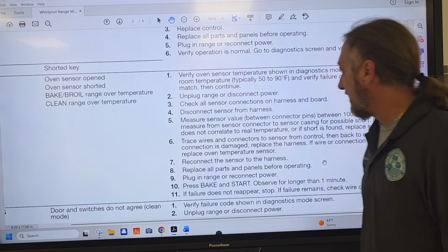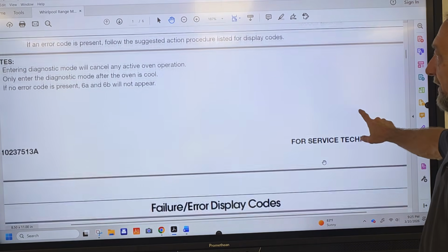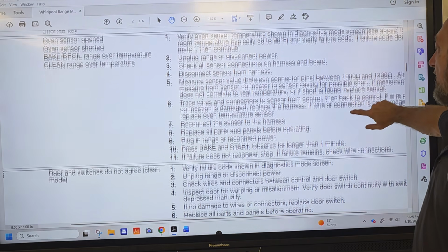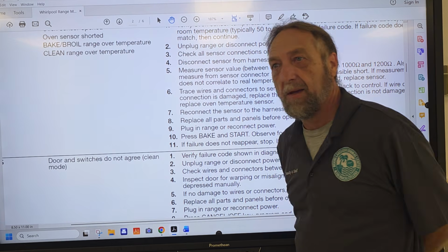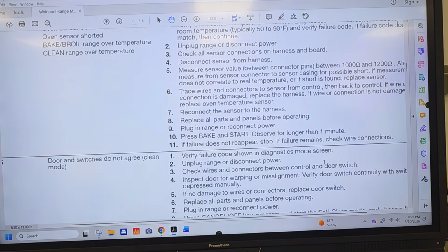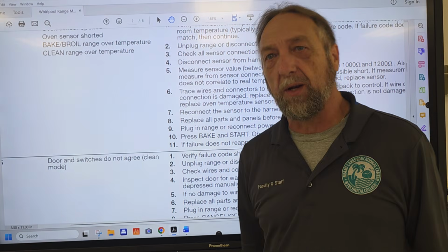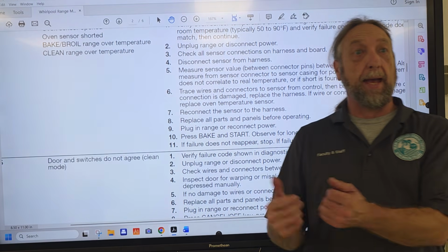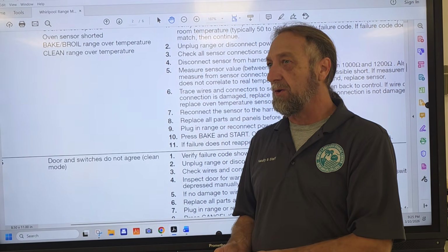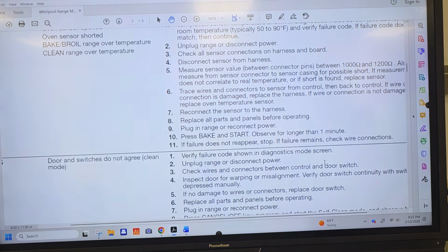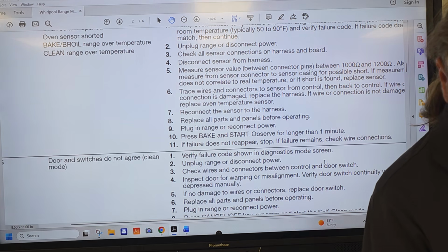The one that says if the sensor reads 500 ohms, what does that mean? It's shorted, it needs to be changed. It's a shortage. I was looking to see if it's written there, but if they're telling you at room temperature it's supposed to read 1,000 ohms and you test it and get 500, it's bad. I saw that question on the paper. I highlighted it.